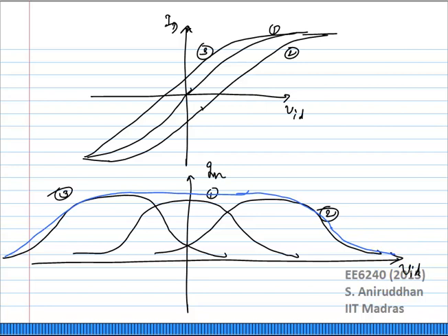Okay. The reason, of course, this is called a multi-tanh circuit is if you look at a bipolar transistor, the differential current to voltage behavior is a tan hyperbolic behavior. So therefore this is called the multi-tanh circuit. Okay. So we will stop here, and on Monday's class, we'll finish up on this nonlinearity of the mixer, and we'll start off with mixer noise.